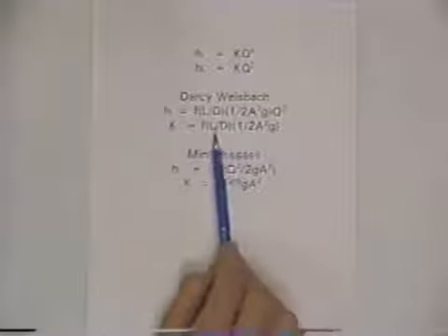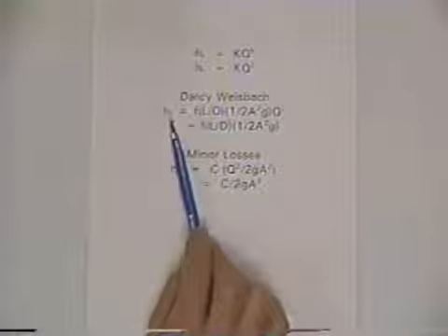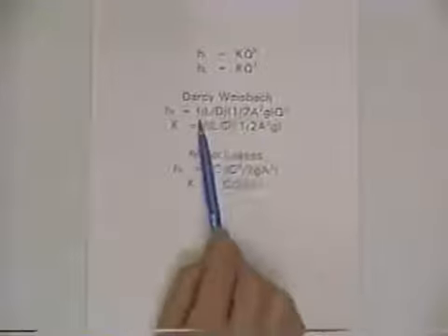We've looked at problems dealing with one pipe, and let's think just a bit about pipe systems, pressure conduit systems that entail more than one pipe. And to do that, it's going to be convenient to express a relationship between head loss and discharge. And we've worked with this already. And so in Darcy-Weisbach, for frictional head losses in a pipe, we're looking at F for frictional head losses.